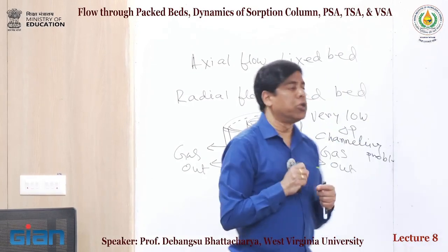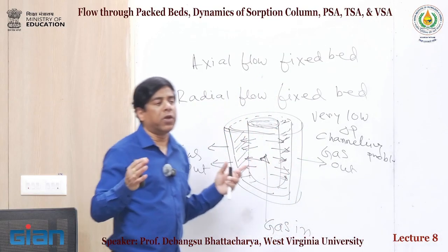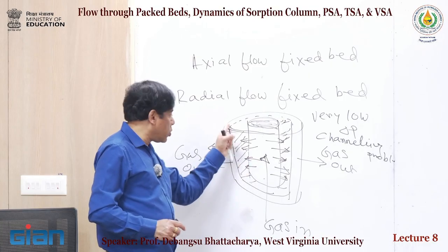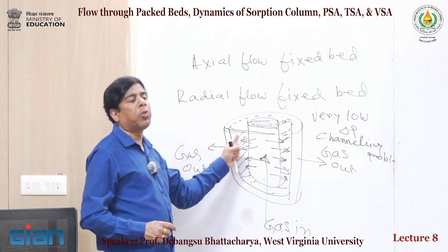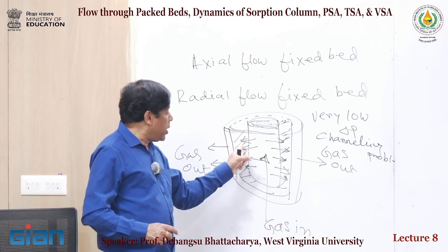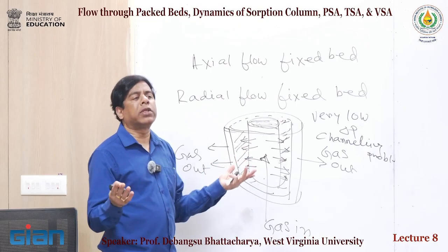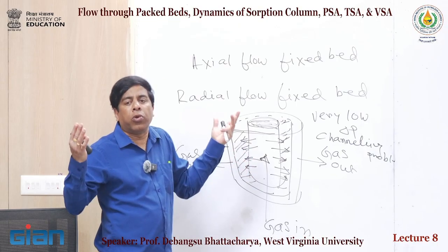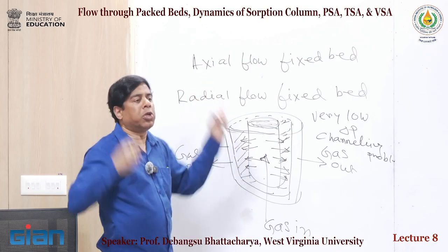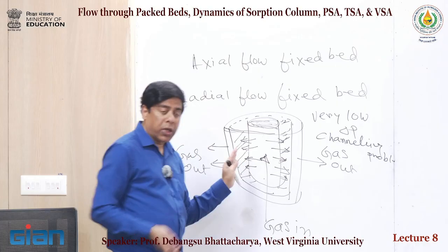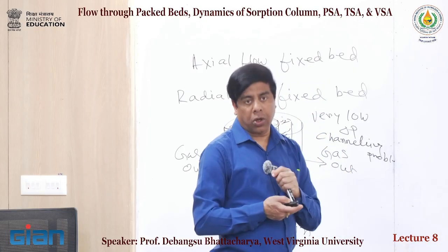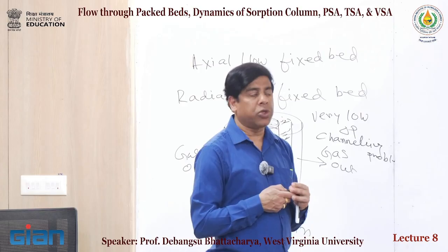If you have a low concentration of CO2, you want a very high residence time to capture it. So you will push it from this side, so that it has a very high residence time when the partial pressure is high. So this portion of the bed will capture more. Here it will speed up, but you also have less material there, so you don't worry about it. It has to be measured given your flue gas or the gas concentration of CO2.